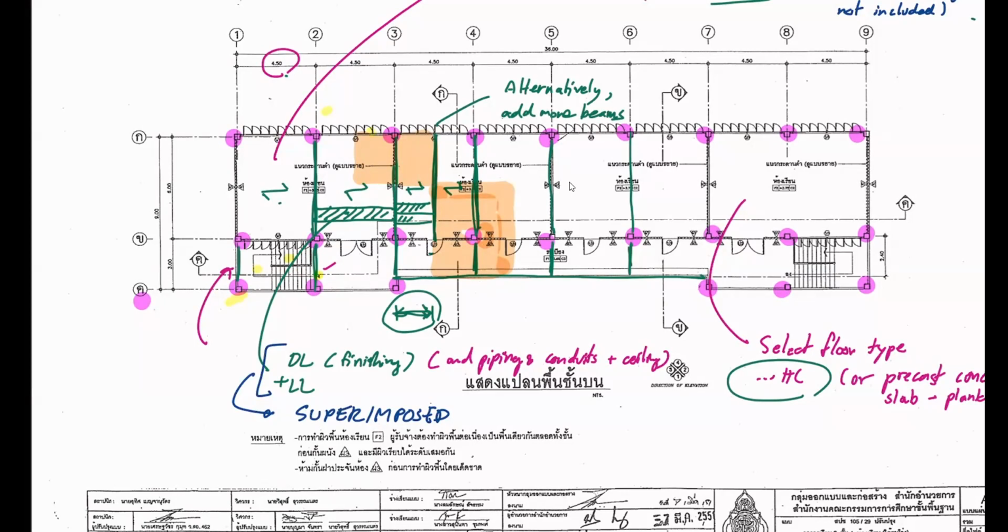Generally, we're going to put the floor in this direction to reduce the moment. Because most of the weight will travel directly onto this cantilever portion. The weight of the floor will go on directly here, not on this beam and then go back here. If you put the floor in this direction to be supported by this beam, the point load for the cantilever portion is going to be huge. So the best way to minimize the load is just to put the floor in this direction.